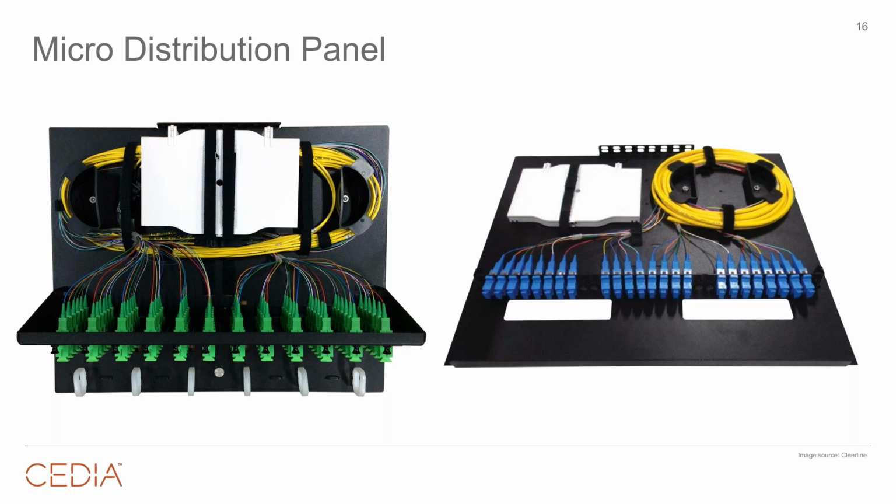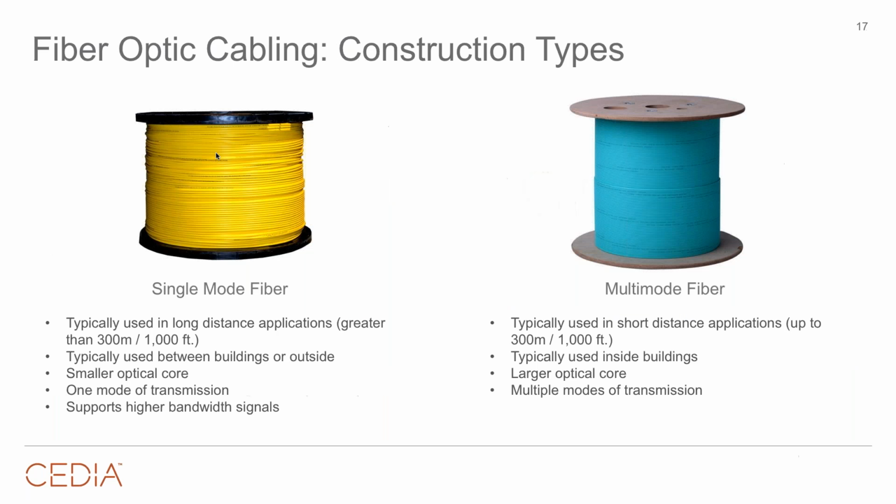95% of the applications out there use duplex fiber. That tends to be the standard. That is the 2-strand duplex riser rated cable. Now, obviously you see plenum, you see outdoor rated, you see tactical, you see all kinds of different other variations in there, but the vast majority of the time it is riser rated, in-wall rated, duplex fiber being pulled from point A to point B.